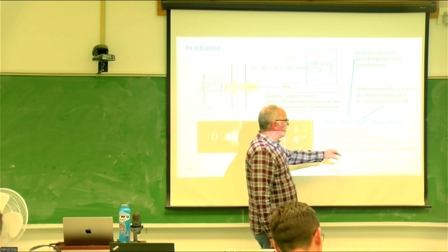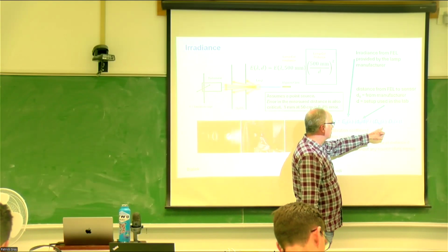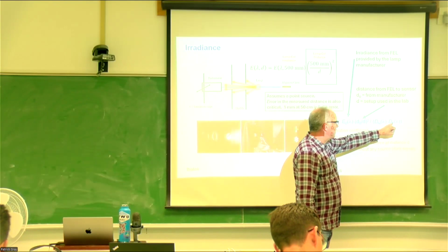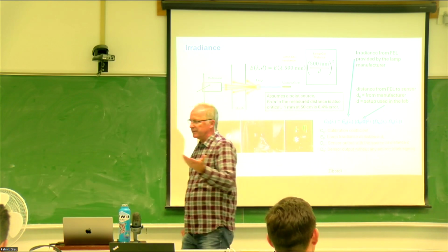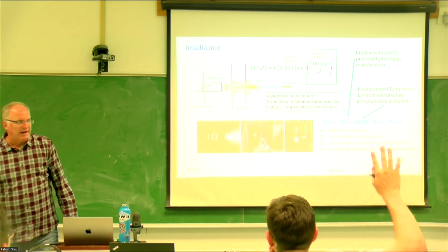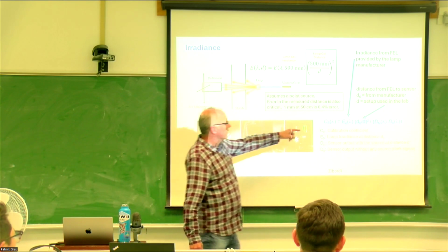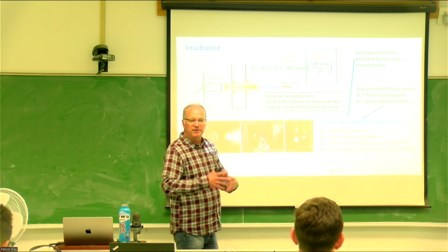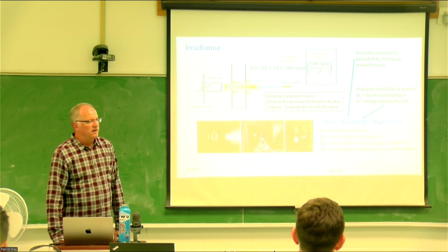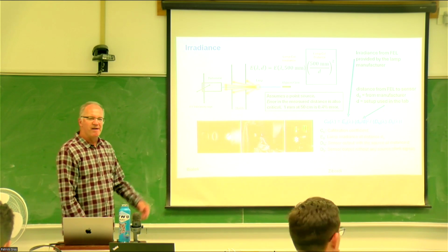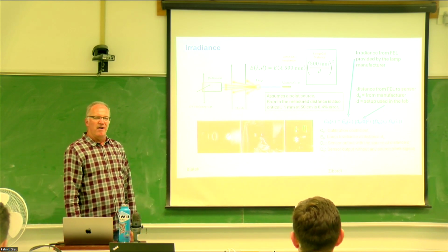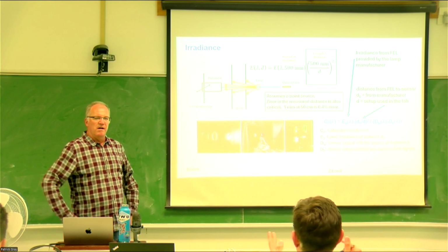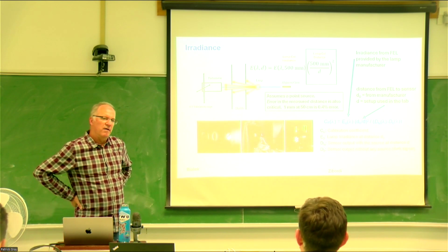So then it's just taking the signal output, the actual measurement value minus the dark counts of the instrument, the noise floor of the instrument. And that derives the actual calibration coefficient that's used to calculate. Why do we have confidence in the lamp radiance value?